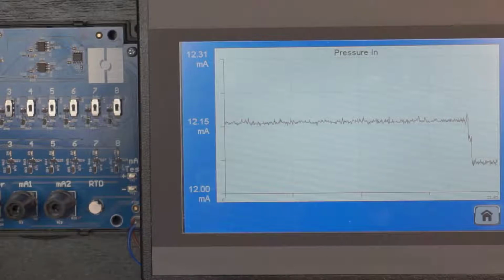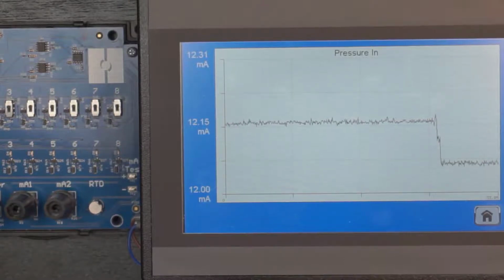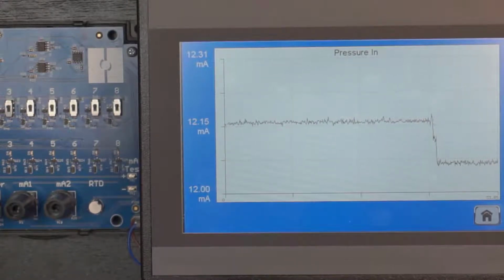But again, I think for a lot of applications, this is a good starting point for the whole responsiveness versus stability trade-off: just going with a moderate value of digital filtering, let's say a value of 3, which I've done here. So that shows you how easy it is to take advantage of the low pass filter that's built into the I/O configuration in every OCS.